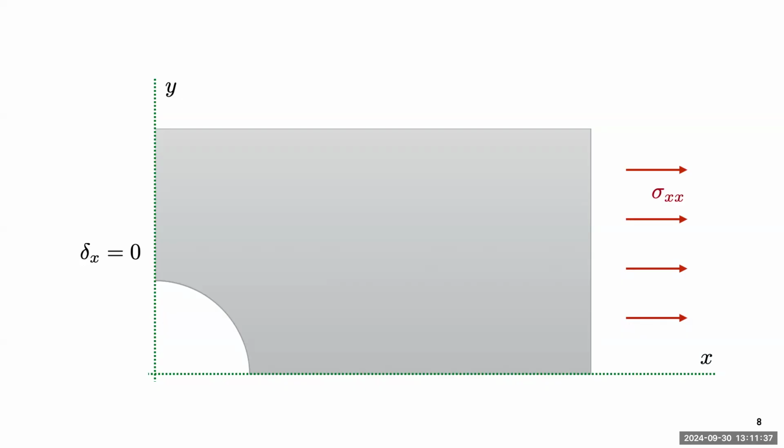So the normal displacement, which is the x direction here, is 0, and the y direction will be the normal direction. If you draw a normal perpendicular to that, it will be 0. Any material on a symmetry plane has to stay on it. So that gives us a condition about the normal displacement. The normal displacement has to be 0. So Abaqus is just enforcing that the normal displacement is 0 when we select the symmetry plane.